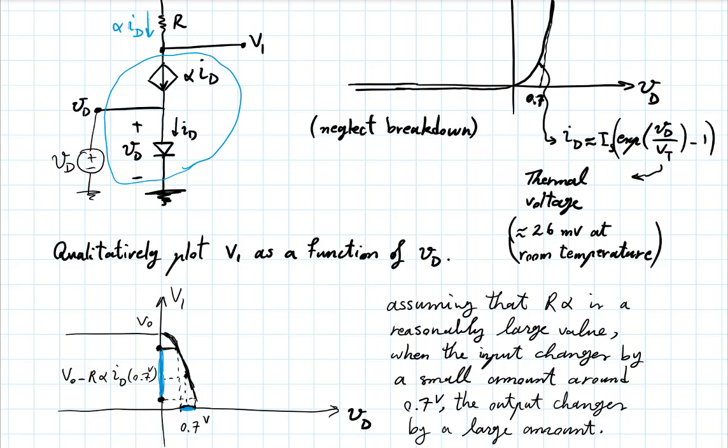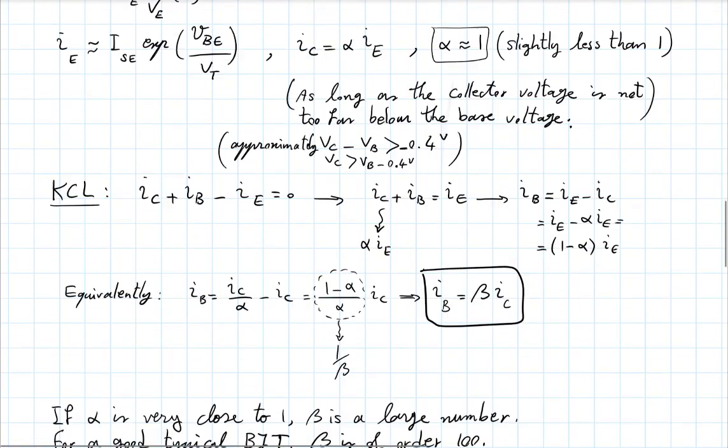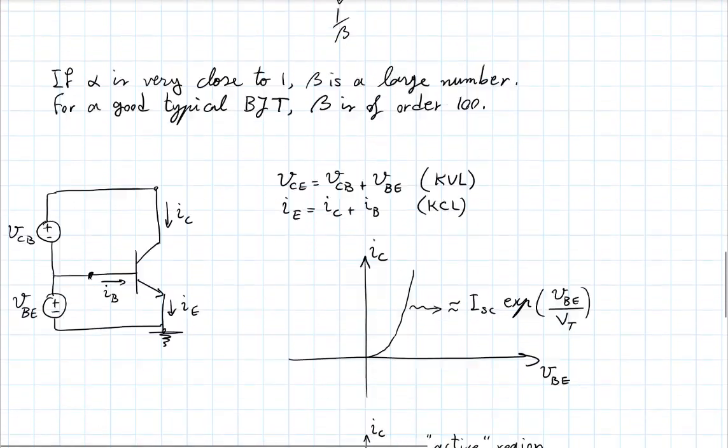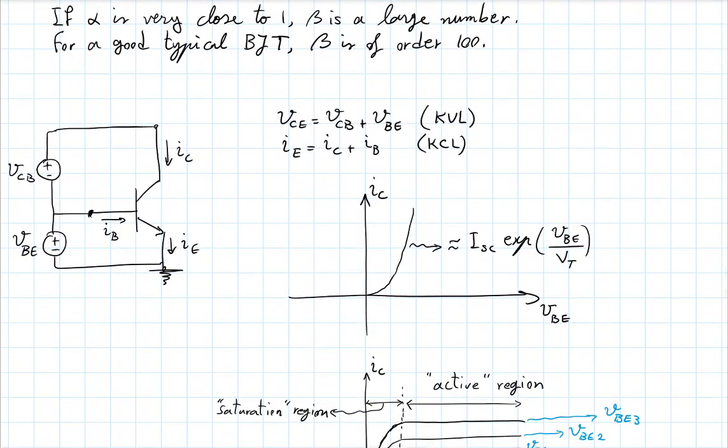And then there is everything you can think of building up on that. By the way, how can I make a diode out of a transistor? Take just the transistor element itself, and make a diode out of it. How would you do that? It has a diode inside, but you want to open it up and break the collector junction, and that would be a little painful. Do something from the outside.